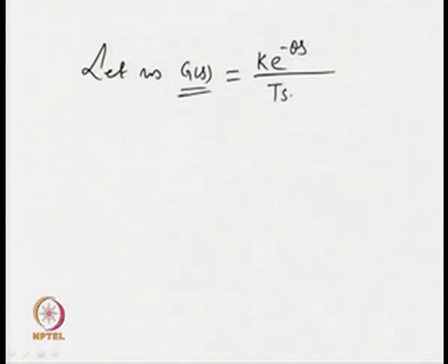Okay. So, let us assume for this case that the plant is a second order system, where the dynamics of the plant is given by G(s) = K e^(-theta s) / (T s + 1)^2. So, I am not using an unstable plant in this case.